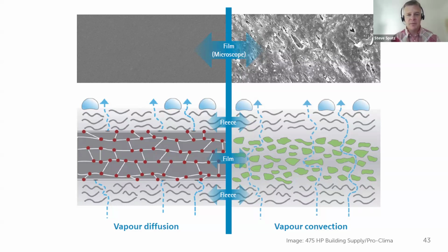But significantly, as a difference between manufacturers, spun polypropylene WRBs, like the Tyvek and the Typar, some of the original WRBs on the market, versus felt, are designed so that vapor transmission occurs through very microscopic small holes in the material. The material is a spun polypropylene, so spun or stretched or put under heat, which creates these little micro tears and holes in the material, which is the intended mechanism for vapor diffusion through the material.